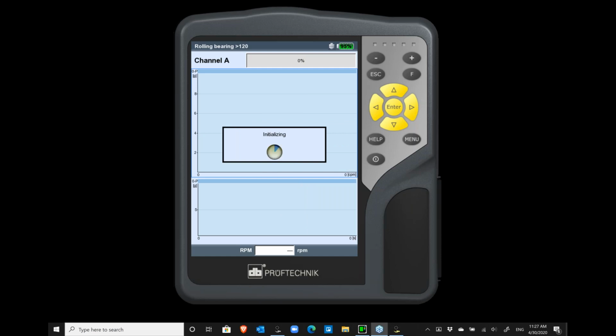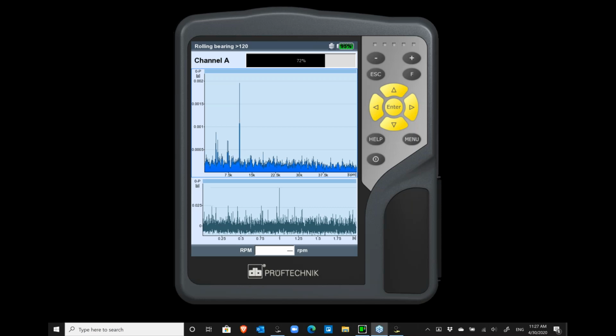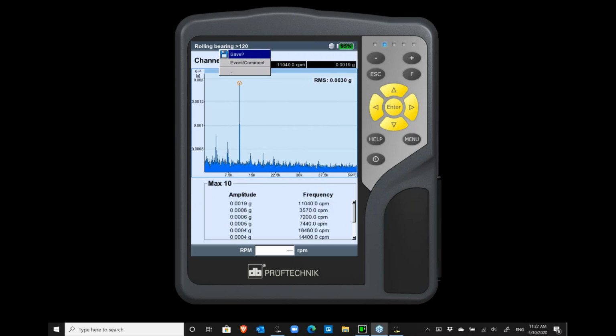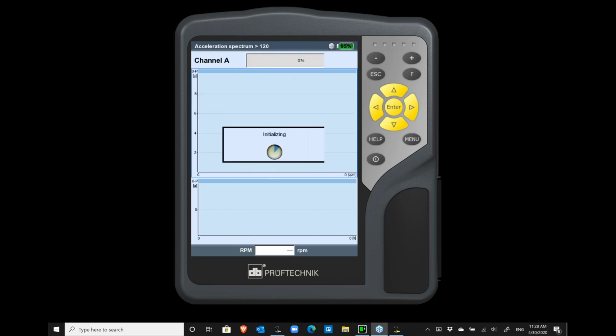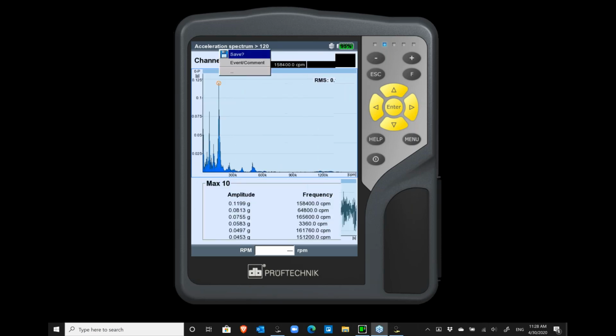This is a really useful tool, so you're not day in, day out collecting data where you're taking lots and lots of time waveforms and lots of data. You can set up adaptive tasks to only take extra special readings or high resolution readings when you need to. Okay, so that's how we do that, the triac setup, as you saw.